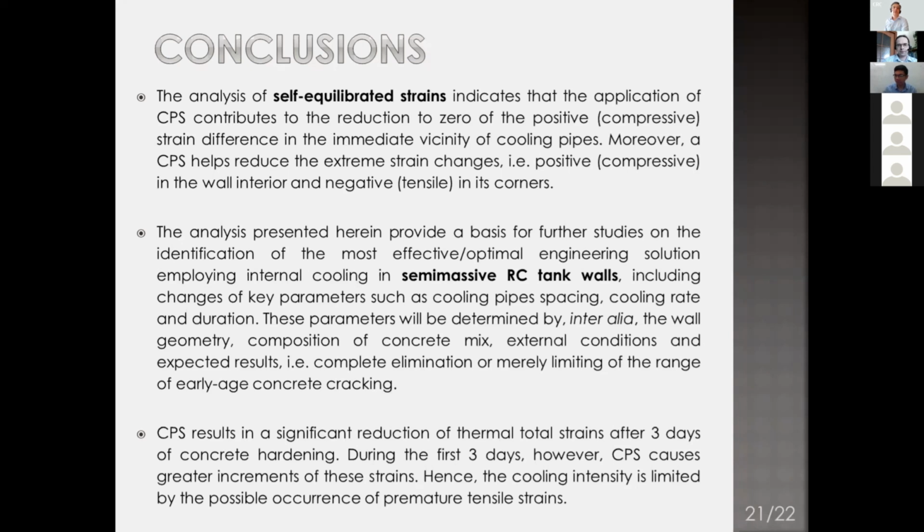The analysis presented herein provides a basis for further studies on the identification of the most effective, optimal engineering solution employing internal cooling in semi-massive reinforced tank walls, including changes of key parameters such as cooling pipe spacing, cooling rate, and duration of cooling. These parameters will be determined by the wall geometry, composition of the concrete mixture, external conditions, and expected results, i.e. complete elimination or merely limiting of the range of early age concrete cracking.